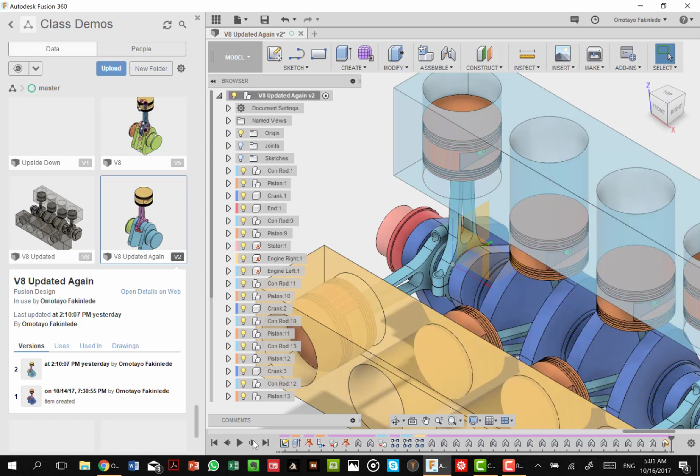And then by the time we do that and capture the positions, and we are happy with the positions we have captured, rotating the individual cranks to the place where we want them, we just decided to make this V8 engine in the simplest kind of firing, by firing the V8 as if there are two sets of 4-cylinder engines, and using the 1342 firing order that we had for the single inline 4 engine.